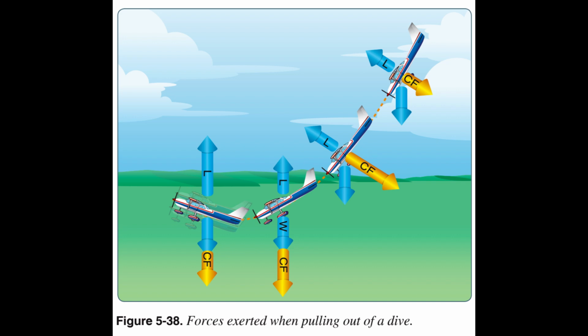One way the aircraft can be stalled in straight and level flight is by flying too slowly. As the airspeed decreases, the AOA must be increased to retain the lift required for maintaining altitude. The lower the airspeed becomes, the more the AOA must be increased. Eventually, an AOA is reached that results in the wing not producing enough lift to support the aircraft, which then starts settling. If the airspeed is reduced further, the aircraft stalls because the AOA has exceeded the critical angle and the airflow over the wing is disrupted.